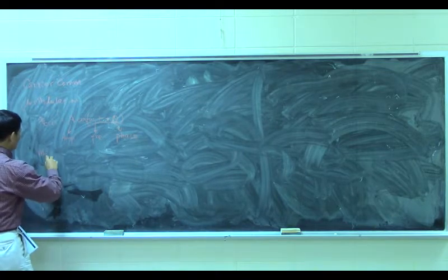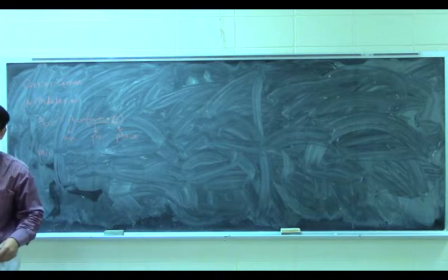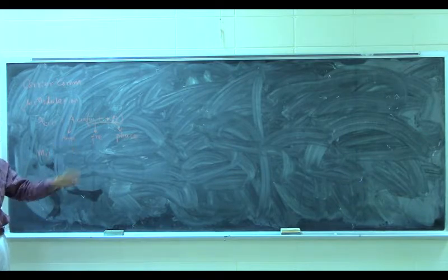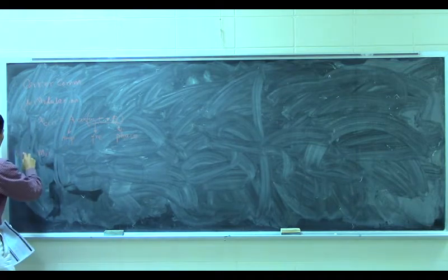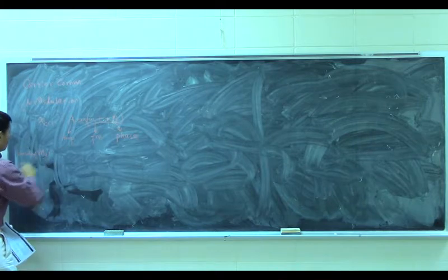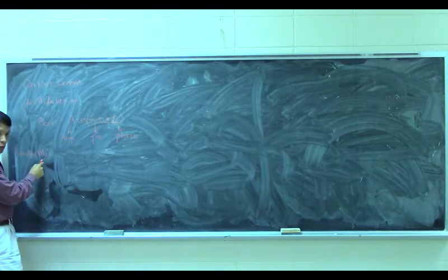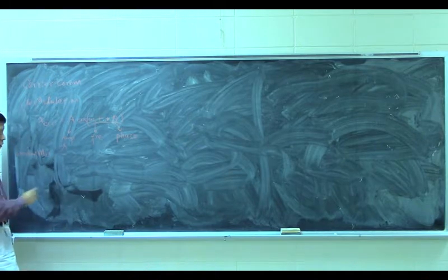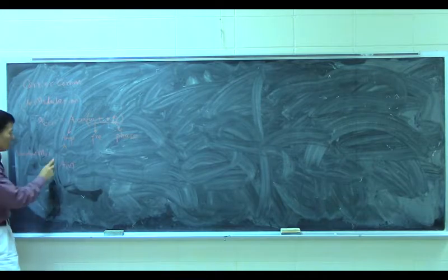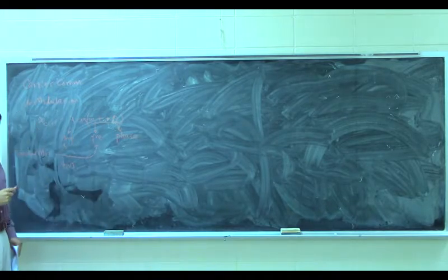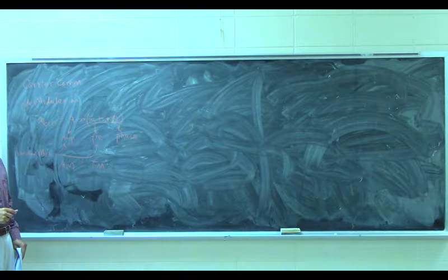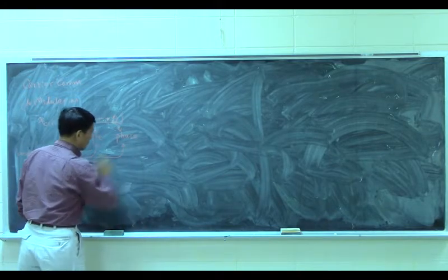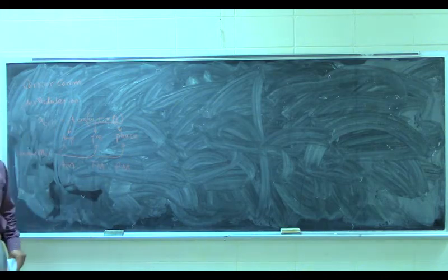Suppose we have a baseband signal m(t), that is the information we want to transmit. Here, my voice, or any video, or the internet signal, anything. This is the baseband signal. If the information is embedded in the amplitude, that is called amplitude modulation. If this information is reflected in the frequency, then this is called frequency modulation. Then if this signal is in the phase, then this will be called phase modulation.